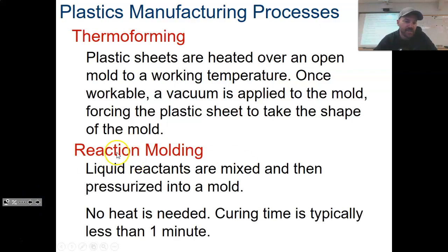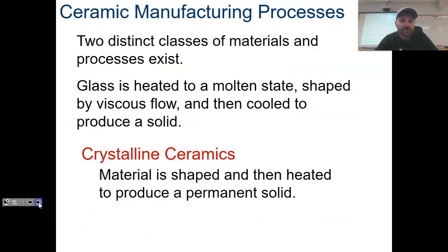Reaction molding, where you can use chemical reagents. I used to do reaction molding; that's how they ship a lot of stuff. If you ever get a box that's got foam around it, we would put our part in there and they would inject in this foam that would expand and then harden. And so they would actually mold it to the box so you wouldn't break your really expensive part through shipping.